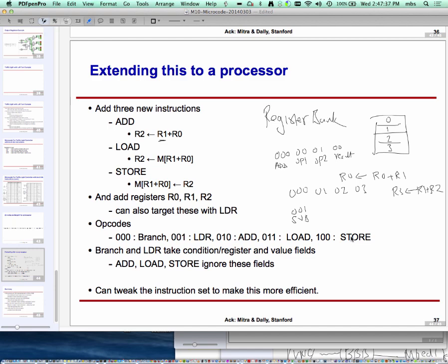Typically, as I said, when you buy a CPU, it comes with a fixed instruction set. But when you are designing your own chip, then you can define the instructions. And then you are designing a processor whose instructions are customized to your application. And there are tools which help you do that. So for example, let's say my application uses some complex operation a lot. Maybe it needs to take sine and cosine of angles a lot of the time. So maybe I can define a processor where sine and cosine are instructions. Normally they are not, because they are rarely used. You can fake sine and cosine by doing addition, multiplication, subtraction, and all.